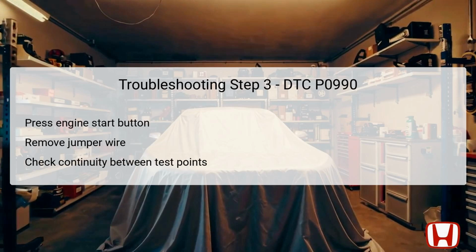The final troubleshooting step requires specific attention to the vehicle's wiring integrity. Start by confirming the vehicle is in off mode, again, by pressing the engine start-stop button. Next, it is necessary to remove the jumper wire that was connected during the previous step. The next procedure involves jumping the Special Connector System, SCS, line using the HDS, which assists in ensuring that the diagnostic process is streamlined properly.